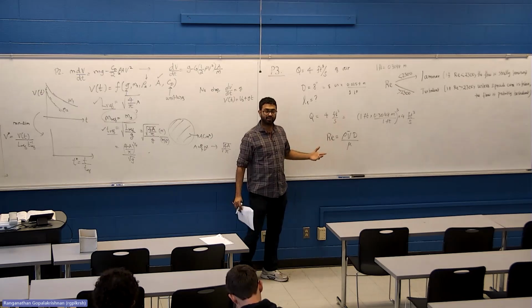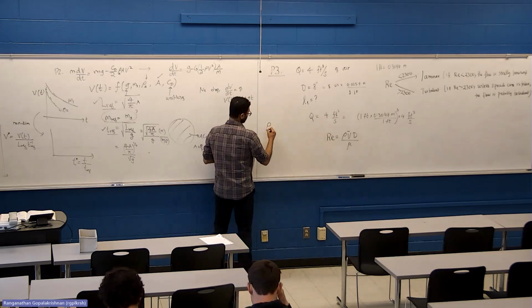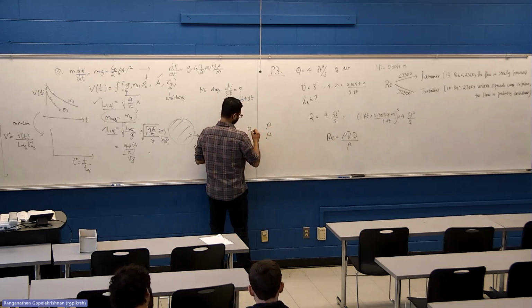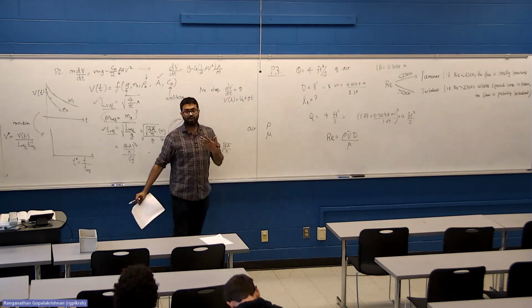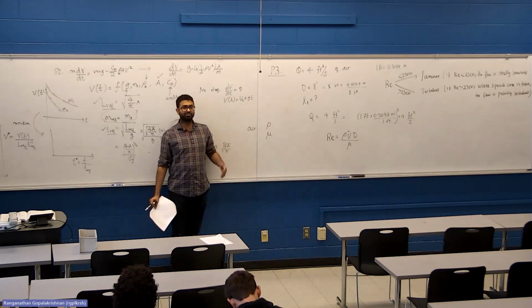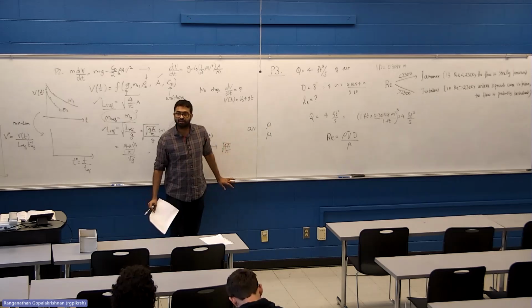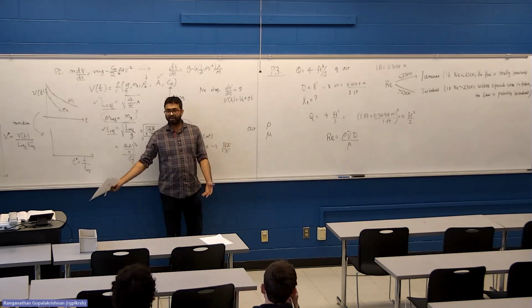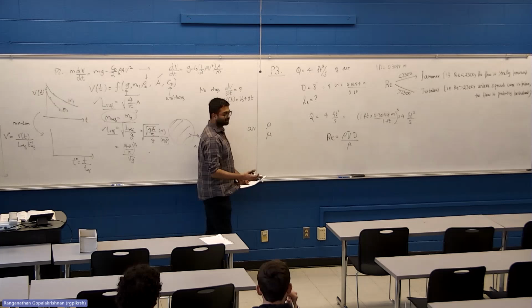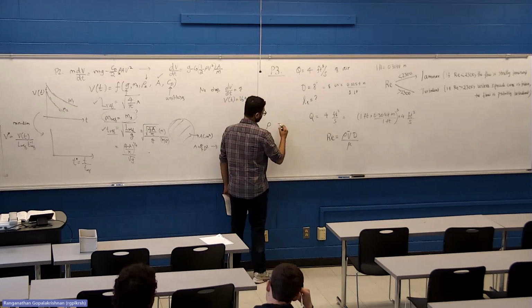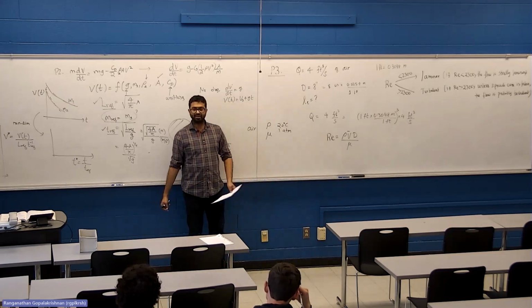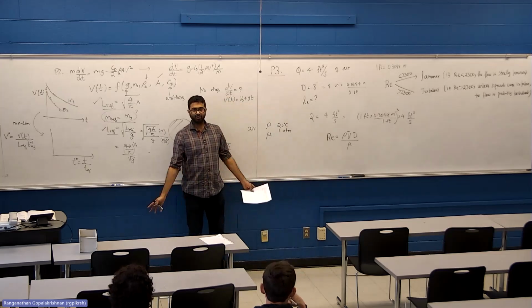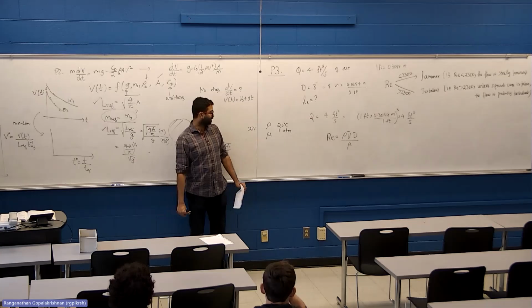So essentially, the problem starts with you trying to calculate each of these quantities for the situation here. So what is density and viscosity for air? Nothing else is told, it just says air. So what's your baseline assumption to be about air? Room temperature, standard temperature and pressure. You can assume something nominal. You can think it's like 20 degrees Celsius, 1 atmosphere. If you did 25 or 30 degrees Celsius, that's also okay. There's no harm in that.